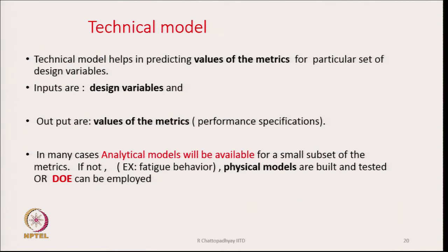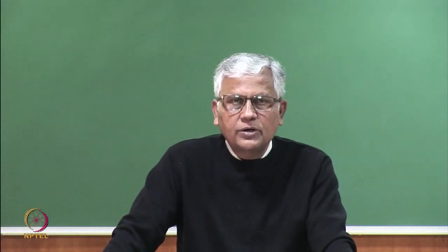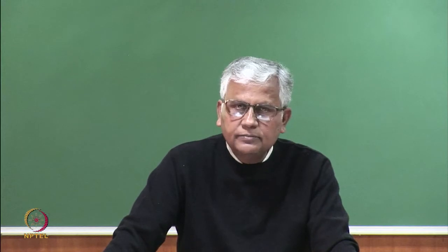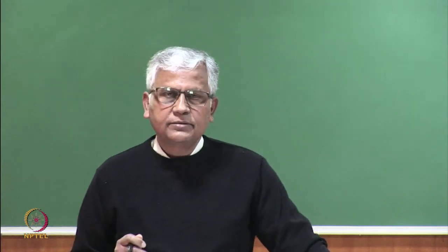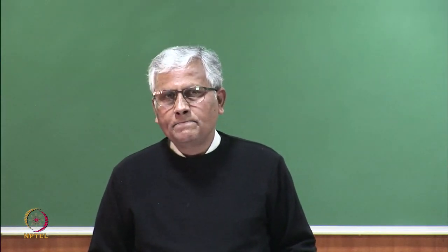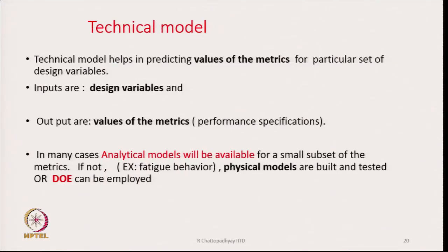Now, fatigue behavior. Sometimes there may not be any analytical model available for predicting the fatigue behavior of textile products. And let us say in which product fatigue behavior will be important. Tire cord is one example. Tire cord is subjected to repeated extensions within the tire when the car is running. And it will be interesting to know the fatigue behavior. Fatigue behavior of a textile rope also will be important.